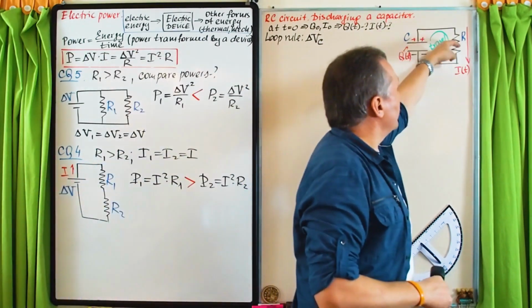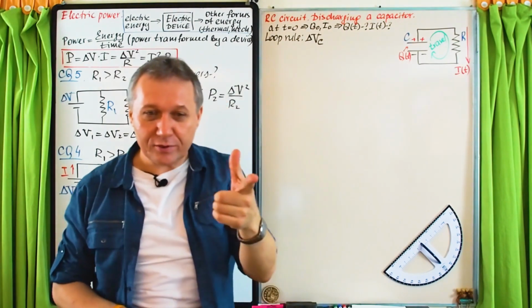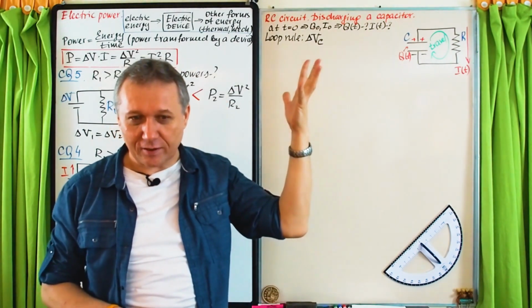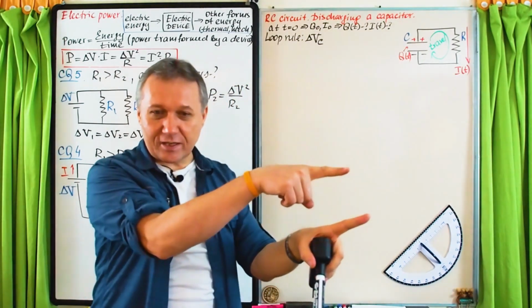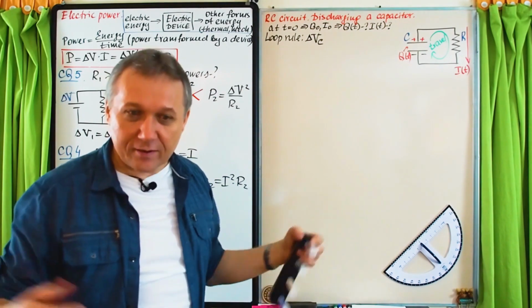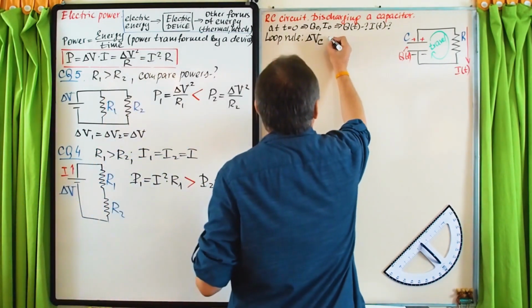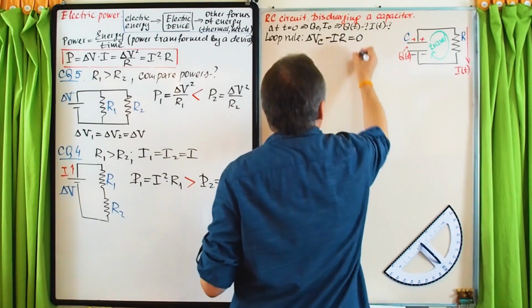Then we cross the resistor. Travel direction down, current direction down. Rule number 3, from the previous recitation class. Contribution minus IR, right? When directions of current and travel in the resistor are the same, contribution is negative. So minus IR. Okay, and that's it. There are only 2 elements.